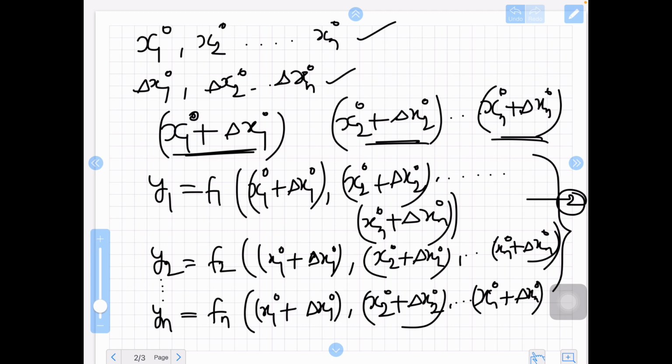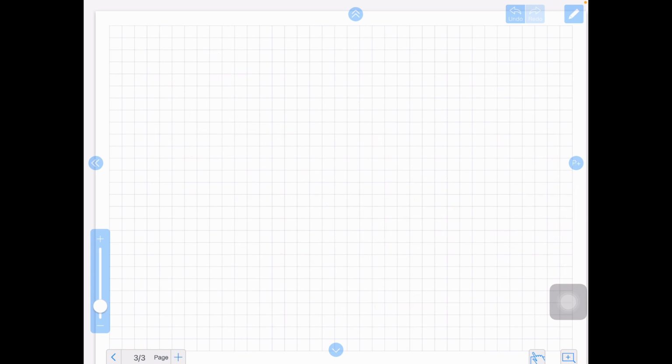So now what we will consider is the technique of linearization of these nonlinear equations by using the Taylor series expansion. Here we are linearizing these nonlinear equations using Taylor series expansion, and we will consider only the first order terms. The second and higher order derivatives we are neglecting because it becomes more complicated. So equation 2, let us modify by applying the Taylor series expansion.